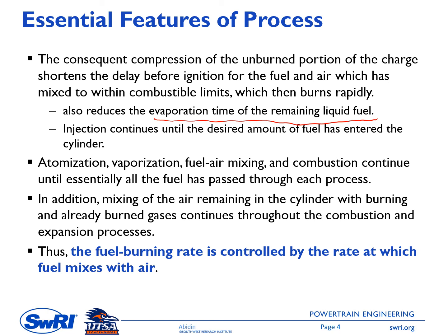So in this case, you will see that the fuel burning rate will be controlled by the rate at which this fuel will mix with air. That's why diesel combustion is also called mixing control combustion.